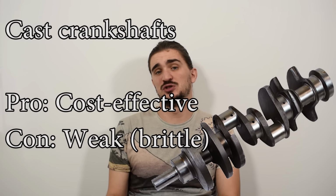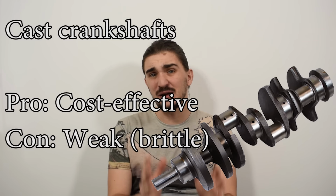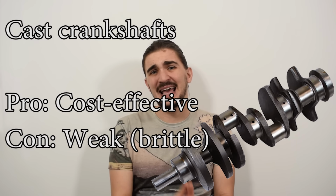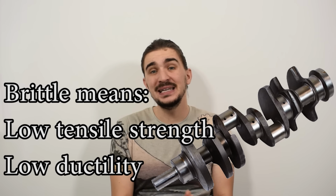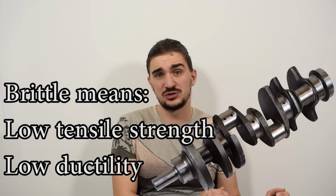Casting is by far the most cost-effective process when it comes to manufacturing crankshafts. The downside is that in general, cast cranks are pretty weak. They're very brittle. Brittle meaning that they have a low tensile strength and a low ductility when compared to forged cranks or cranks machined out from a billet.